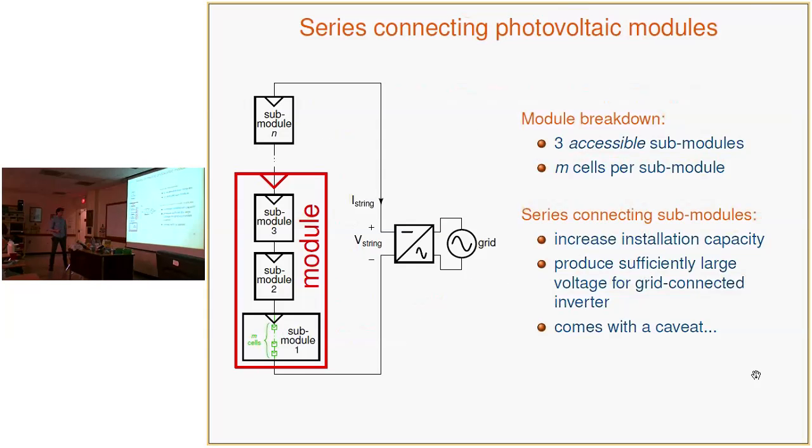Okay, that's fine. So I want to start off with a few definitions. When I say PV module, I mean essentially a PV panel, like a lot of you are familiar with that term. It's interchangeable with PV module. And a module is typically composed of 3 to 4 submodules, where each submodule has a specific amount of series connected cells in the submodule.